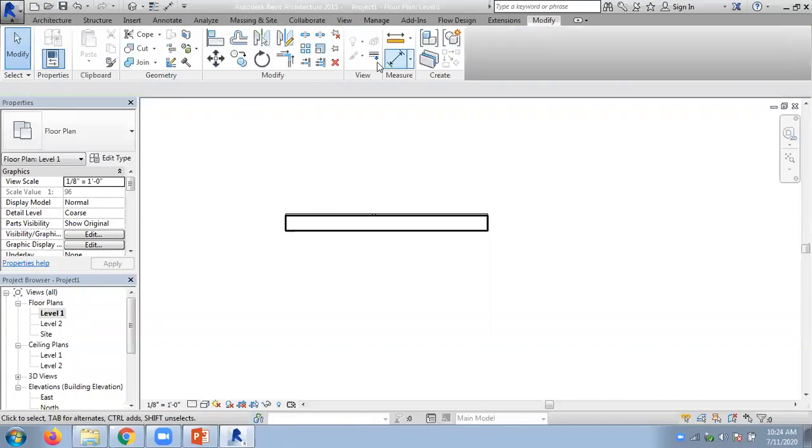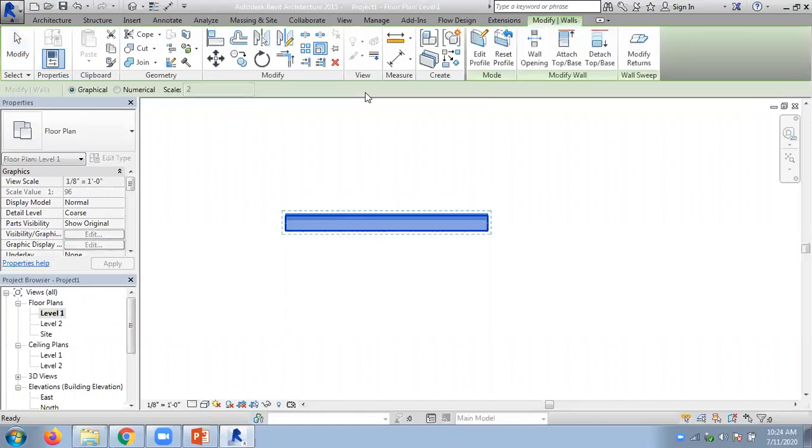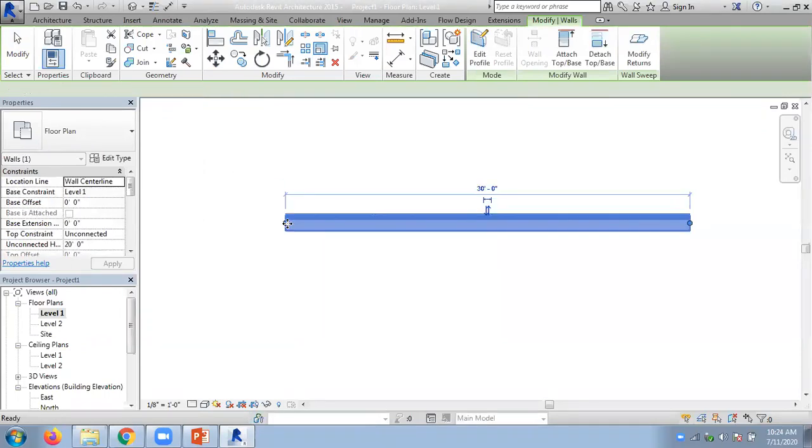So we will look at this. This is the scale tool. We have numerical scales. Select this and enter. If I just apply the numerical scale 2 times, just select the base point something like here. You see it's scaled up, but it's only scaled up in this length direction.